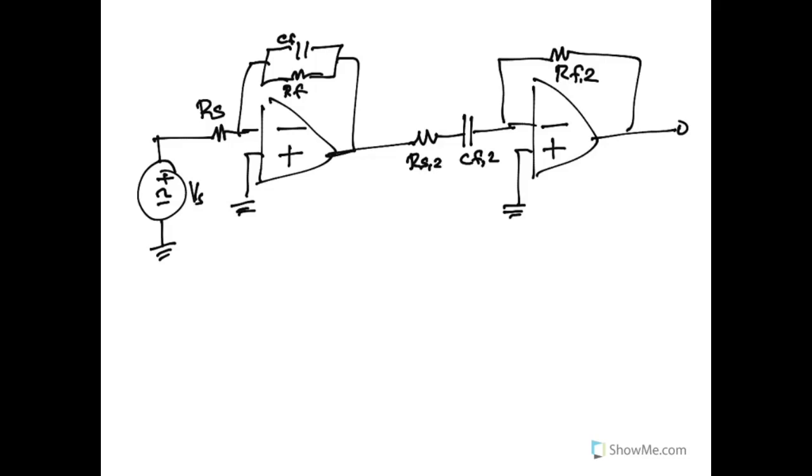So let's combine this knowledge here of active filters and try to figure out what kind of circuit this design is. So if we had these two op-amp circuits combined, what would be our different element? And the first thing to notice is that this is a cascaded filter, so we're going to get some unique behavior by cascading them. And we can look to see where the capacitors are in each of the circuits to figure out what type of filter it is.